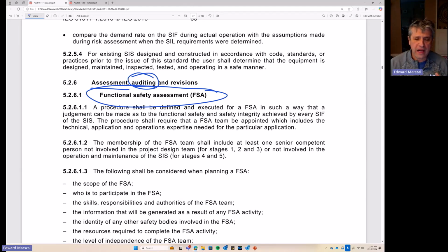No. We agree, we understand, we know human failures are a problem that we need to consider. But putting them in the PFD calculations, I showed you, not only doesn't fix the problem, it leads you to make bad decisions. It leads you to increase your testing. It leads you to increase your redundancy when those modifications will not make the situation any better. They will not improve the PFD.